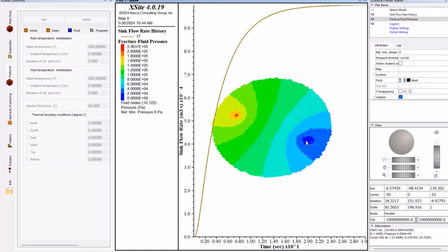In the next step, we run the model to mechanical equilibrium, because by running the model to this steady flow state, we created a certain pore pressure field which is acting on the solid model. We want to make sure that once we start simulating the circulation of the cold fluid, the model is in mechanical equilibrium.